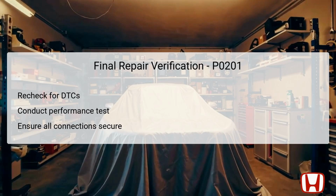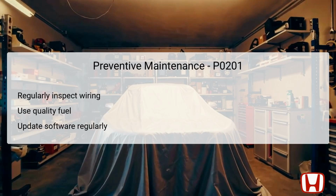In terms of preventive maintenance for the injector circuit, and to avoid potential DTCs like P0201, several proactive steps can be implemented. Regular inspections of the wiring, connectors, and terminals associated with the injector and PCM can help identify wear or damage before they lead to failures.